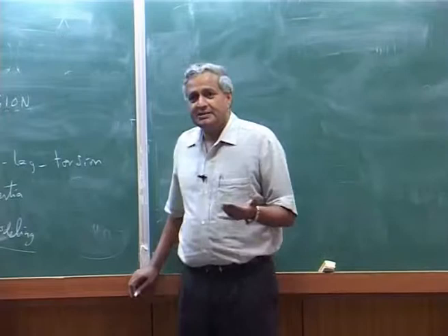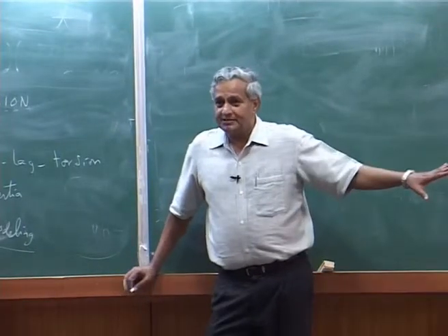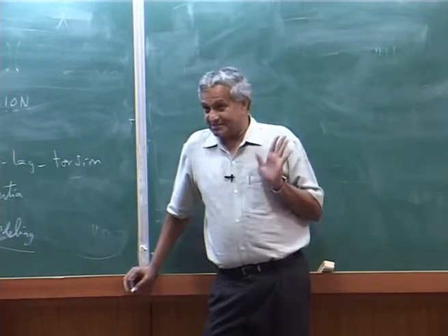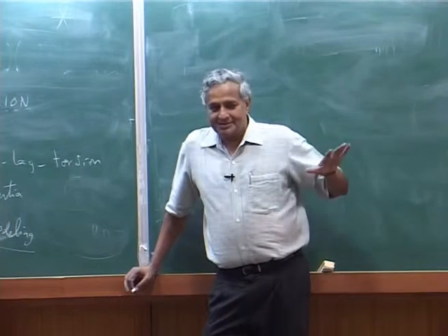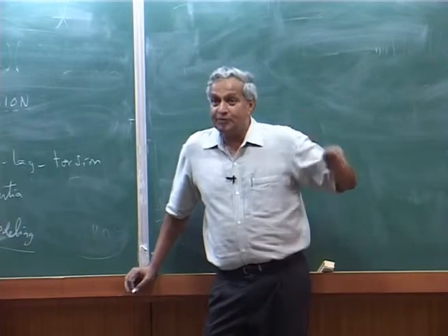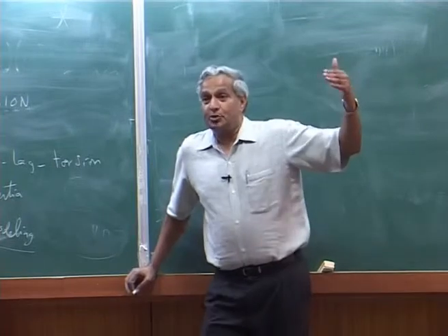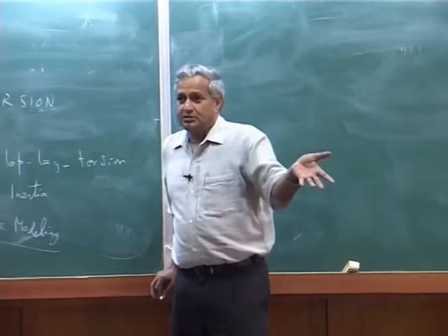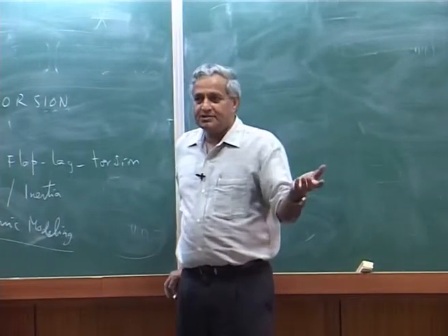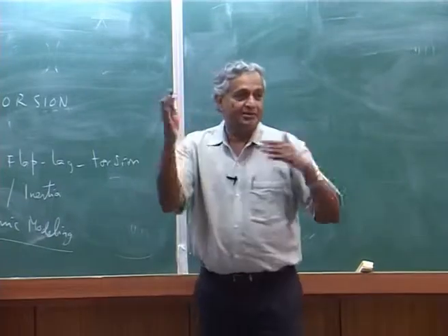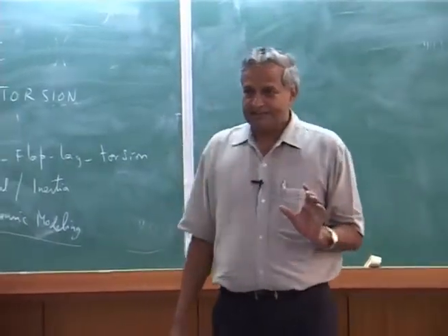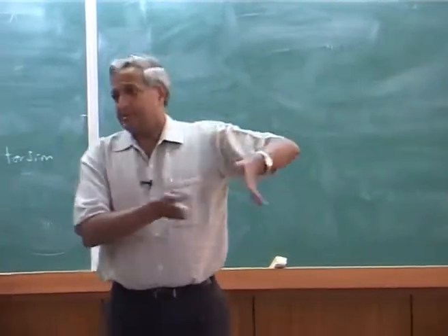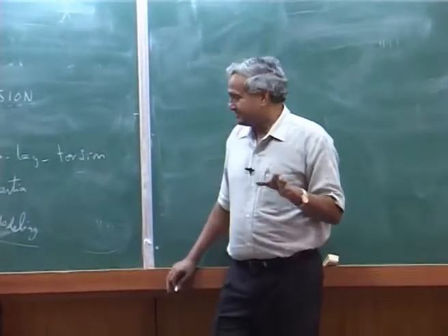Today we have certain models which were developed: dynamic inflow, dynamic wake, etc. These are all global theories. Still I am telling you, it's not CFD per se. But still it is able to give you the variation of inflow when there is a variation in the rotor blade loading. The whole concept started like that. If there is a change in load, inflow will change. When the inflow changes, load changes. How do you relate these two? This is one line of problems. People have spent time on modeling that.